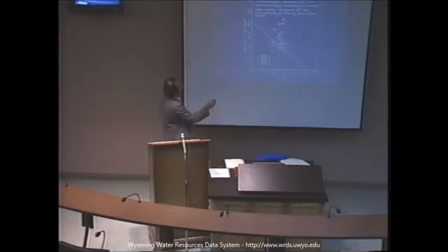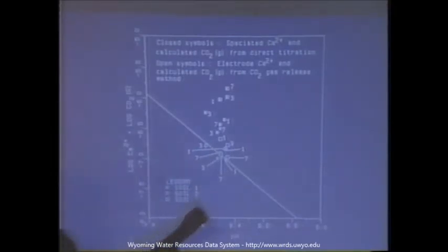Okay, here we plotted log of calcium plus log CO2 versus pH for calcite solubility. This is the calcite solubility isotherm right here. We included 1, 2, 3 soils, and also we used all 1, 3, and 7 days reaction time results here. The closed symbols, again, include your organics and inorganics, and the open symbols are just inorganic calcium and carbonate activities.